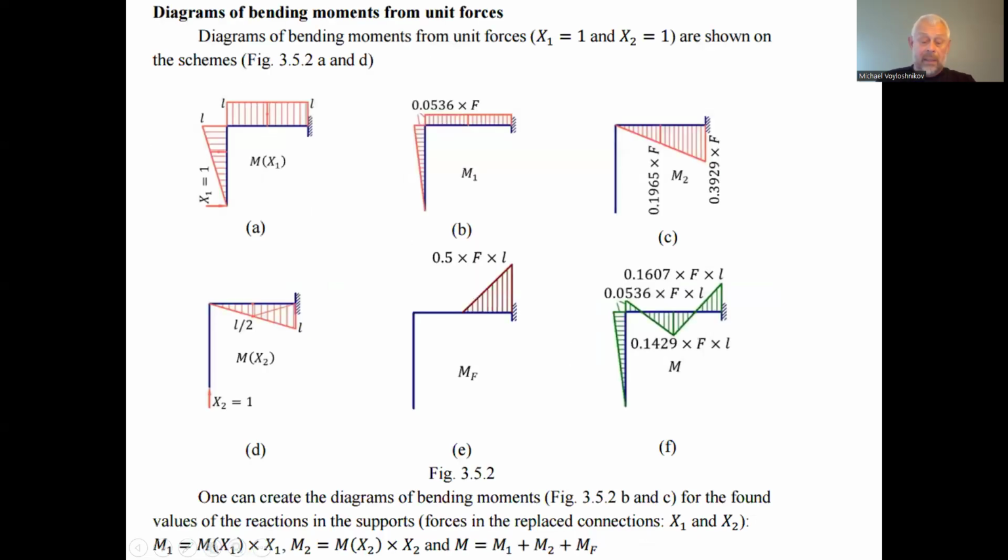Okay, next we can build the final bending moment diagram as the superposition of all considered diagrams of the force in the absent supporting links. It corresponds to the force in the support, actually, due to the compatibility of deformation concept provided by the use of the canonical equations of the force method.